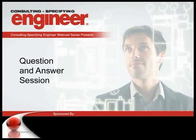Okay. Hey, Jim, by the way, there was a comment from Mark Rogers from Minneapolis saying that the generator curves that you were using do not seem typical of what SKM Power Tools typically shows for generators. Do you have any comment about that? The curves that I presented in the presentation were actually made utilizing SKM. And SKM, just to get into the technical nature of that software, they don't have a good way to model a PMG, so you actually have to manipulate the curve to make sure that it looks like your unit is going to perform with the PMG.